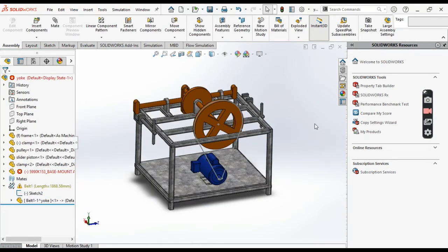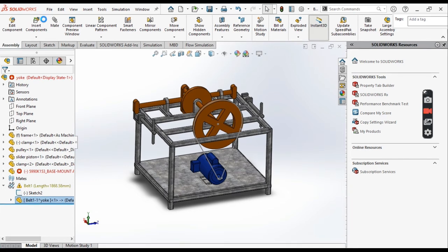After you've created a profile like this and ensured you create a part, you can right click here and choose edit features, or you just open the part. After you open the part, what you want to do is create a belt profile. This task should not be hard for us. We are going to use a sweep command, just the way I've explained the sweep command before. So it's not going to be hard.